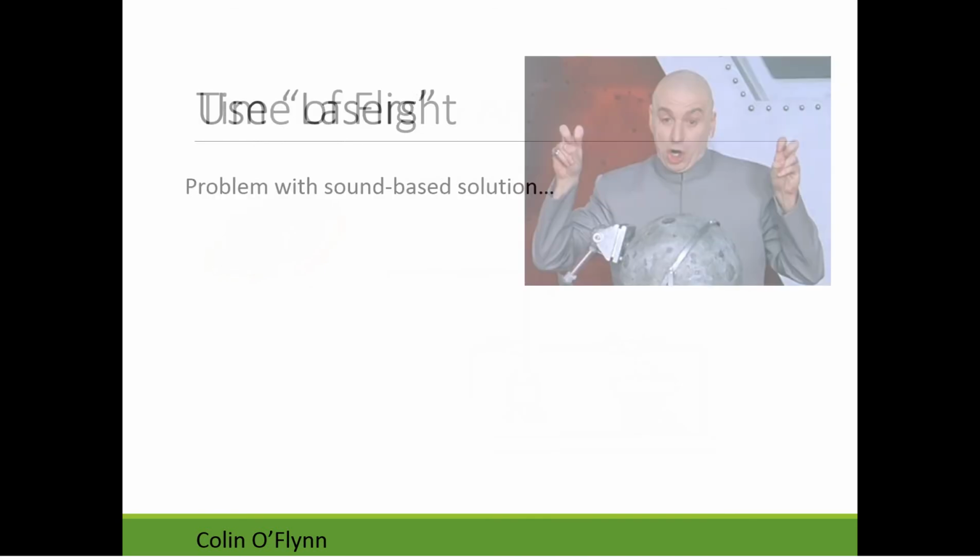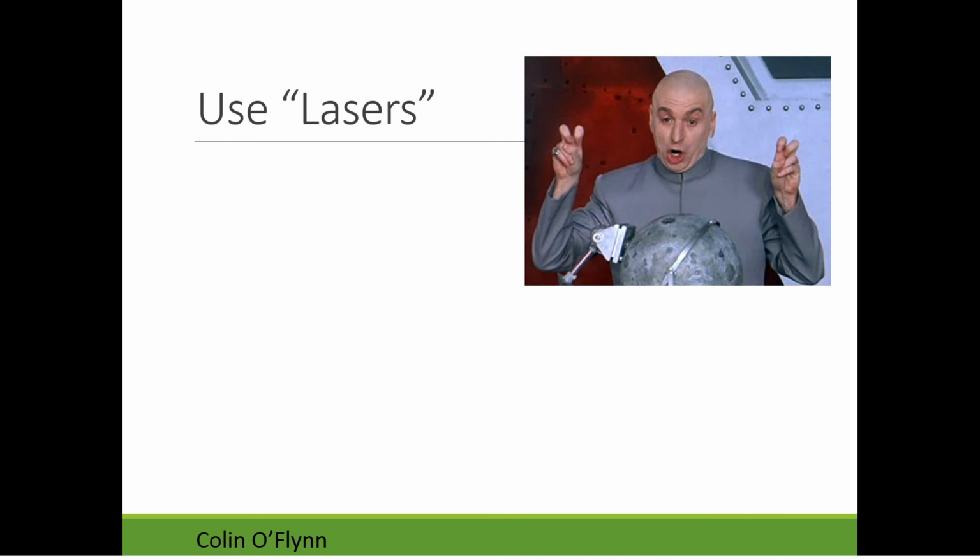You can also do time of flight, and you can use lasers instead of the ultrasonic system. Using lasers is more complicated, though we have the same problem: a transmitter and a receiver. With the ultrasonics, this V is equal to 343, right?